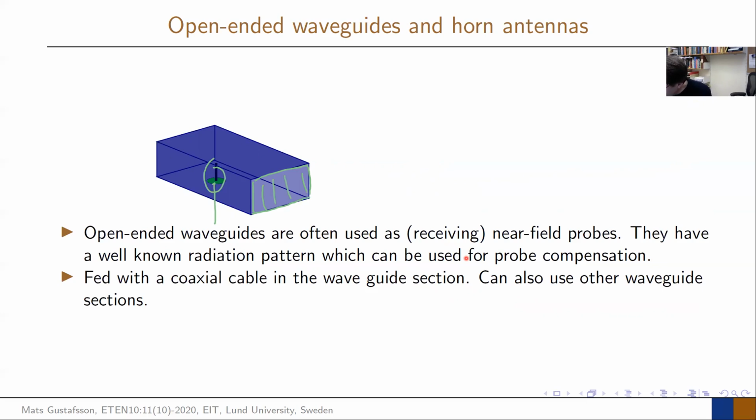And that, of course, generates inside here a lot of electric and magnetic fields. And now they are in a very good environment, because you have this rectangular shape, as you typically have in a horn antenna here, this bottom part here, that is this waveguide section. There we know everything that happens, because here we can actually solve Maxwell's equations, and we'll see it very soon. And then those fields will in some ways move out here from where I generated to the aperture. And then I have a good idea what the electric field is in this aperture.